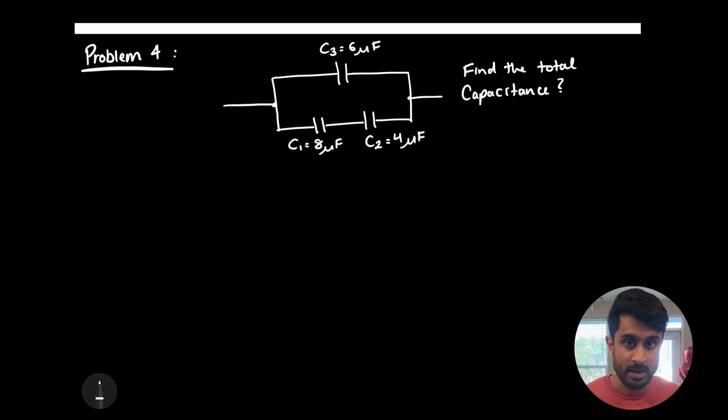calculate the total capacitance. When we calculate the total capacitance, the rules that we use with respect to resistances are completely flipped. When you calculate parallel capacitors, the equivalent capacitances add up. Versus if they're series capacitances, we use the reciprocal rule like how we used with parallel resistors. Let's apply that concept in problem number 4 here.